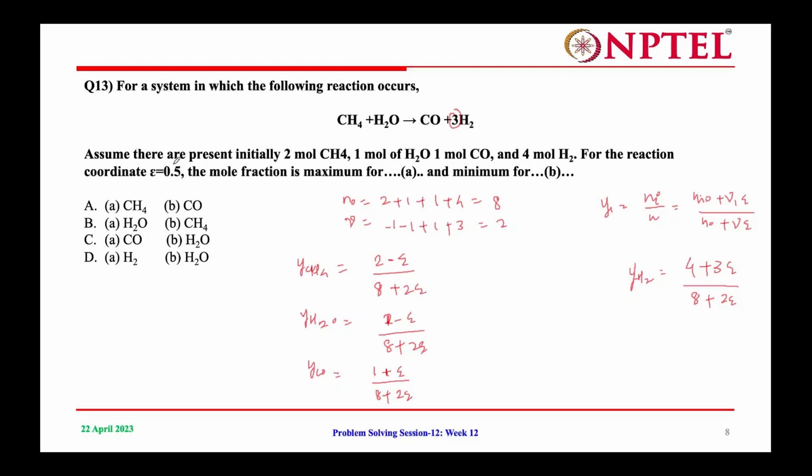Here the reaction coordinate value is given, you put it in all equations. We get 0.116 for CH4, 0.055 for H2O, 0.16 for CO and 0.61 for H2.